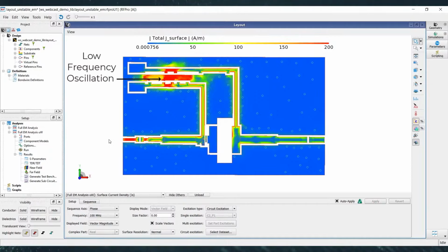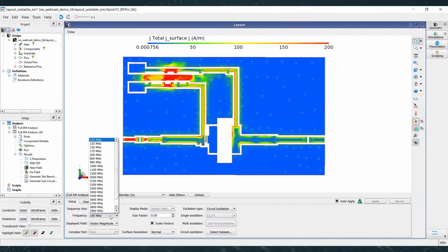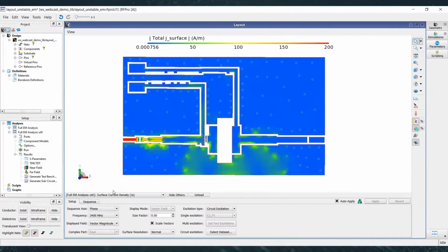And so that leads to the idea that with a lot of amplifiers, you actually have to run load pull, and you try to characterize your amplifier and make it stable over all of these load conditions. So at 10 to 1, 15 to 1 VSWR, you start pulling and seeing if your circuit is still stable under those conditions. And I've got to tell you, that is a nightmare for a lot of our customers. You have this thing stable at 50 ohms, you start pulling a 10 to 1 VSWR, and then you get this Christmas tree effect where all these issues pop up in the spectrum.